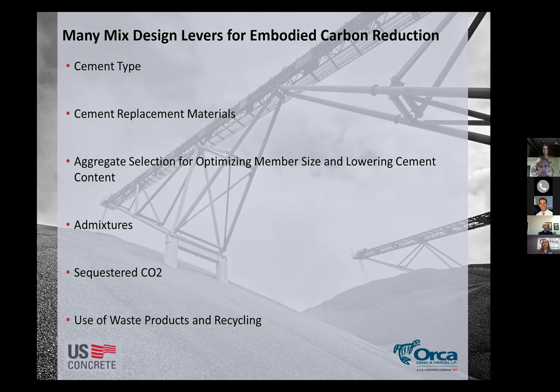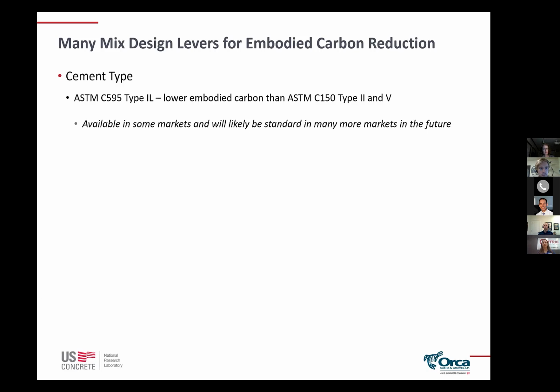And all of this to say, to continue the message of that communication with your ready mix producer is going to be very important, because they're the ones who are going to be able to speak to the availability of each of these types of levers in their market. So the ones we'll talk about are cement type, cement replacement materials, the aggregate selection, admixtures, sequestered carbon dioxide, and then the use of waste products and recycling.